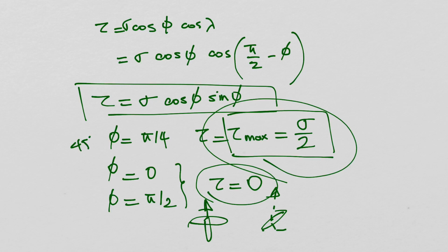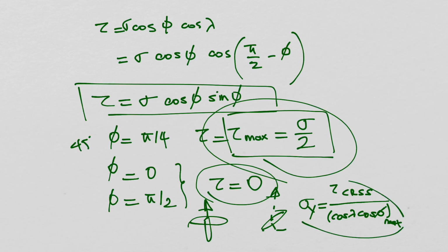Okay. Then, of course, this also defines the yield strength, right? So the yield strength basically is when that shear stress reaches the critical value. That's when the slip happens, as I described. And you will see that when that shear is reaching the critical resolved shear stress at those maximum values of these angles, yielding starts. So that is the definition of yield strength.